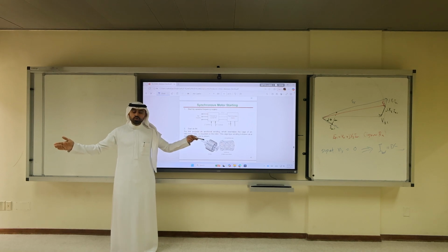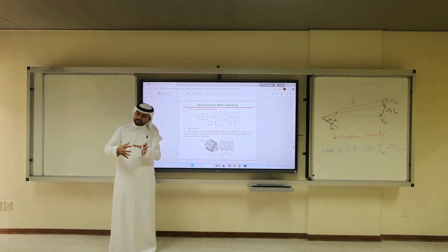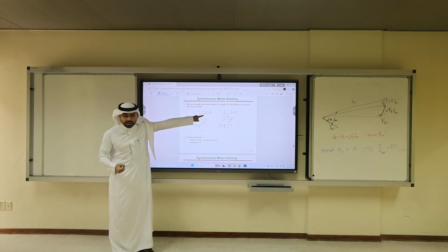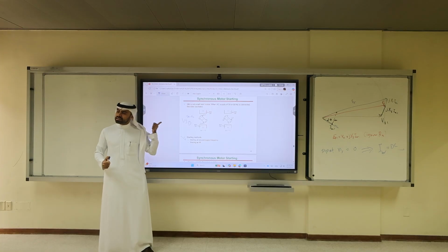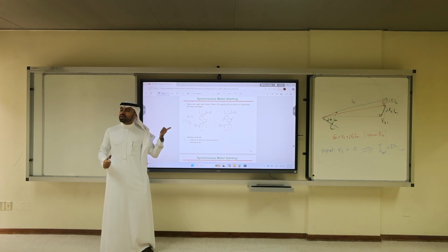But here you have an excited rotor inside, under the cage. This excited rotor would still have this torque T that would maintain the synchronous speed, so it will stay at synchronous speed. The impact of the cage is temporary, only during the startup.